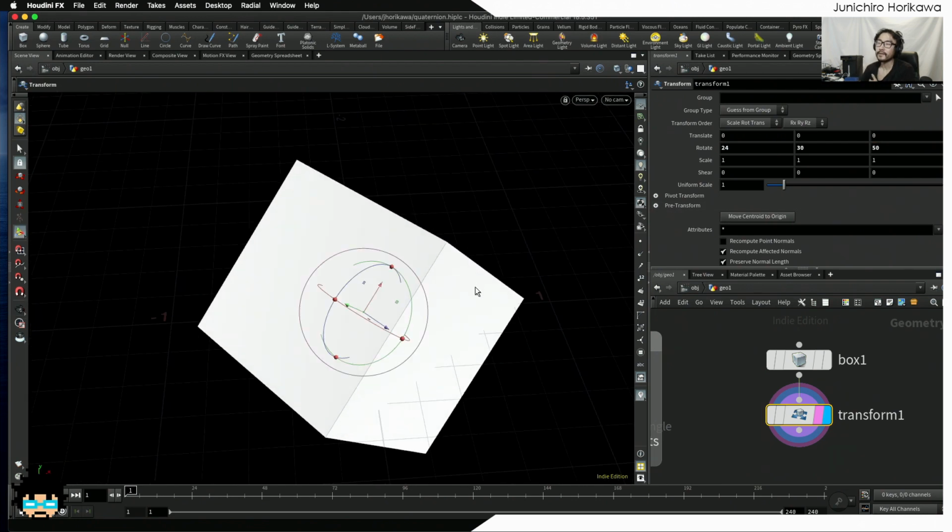And sometimes you might want to rotate the object in this way, and there's a way to do that in Houdini, in VEX as well, by converting this so-called Euler angle into a quaternion. Now the important thing about this is that the rotational order matters. Like in this case, it is rotated first using the x-axis, and then rotating the y-axis, then rotating in the z-axis.